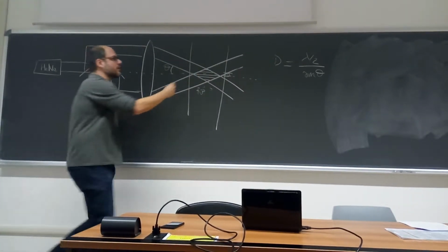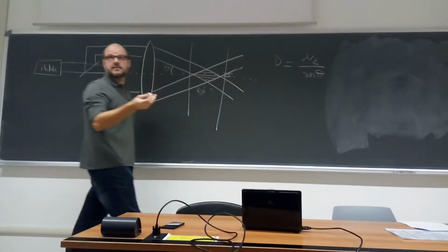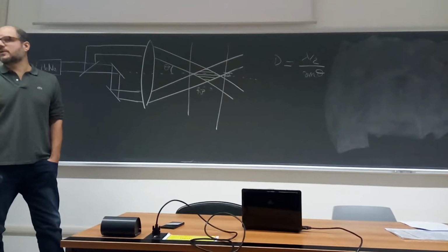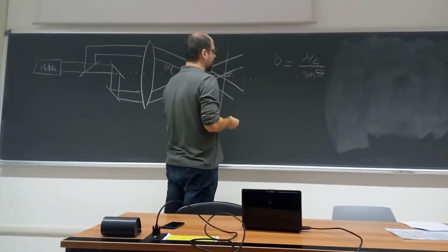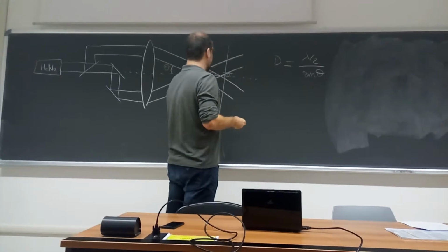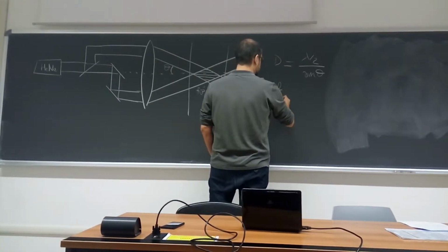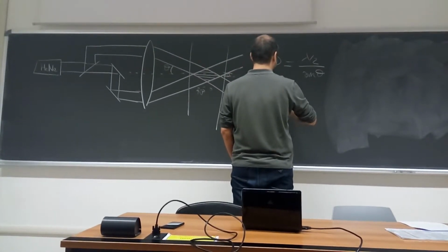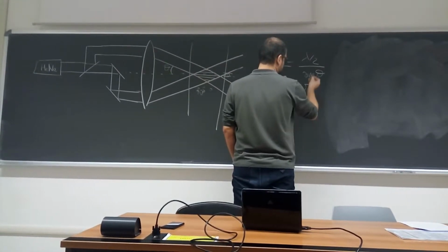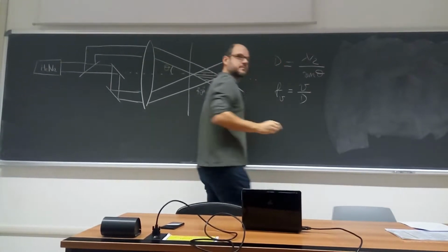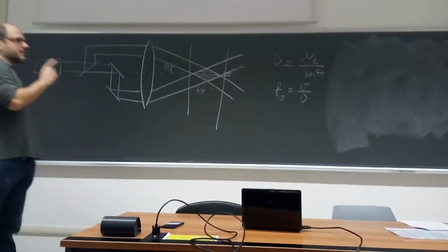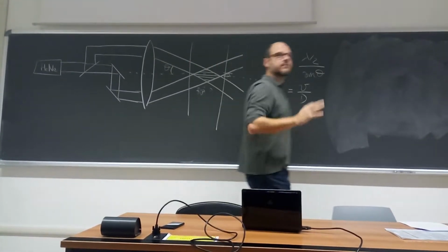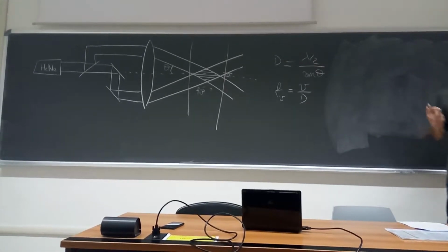If we look at the scattered light onto an oscilloscope, and we look at the frequency of the peaks, we can measure the velocity. Because the frequency is always given by the velocity of the particle divided by the distance d. Is this true? Yes, it's true. So these are the most important things to remember for a laser Doppler velocimeter.